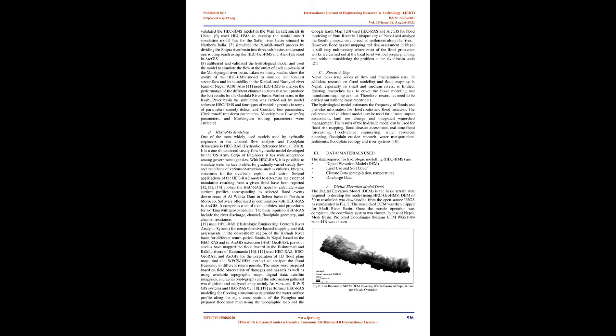The spatial distribution of climate and meteorological data collection stations in the basin is poor. The entire basin is represented by a single set of meteorological component. Therefore, this model used Thiessen polygon method for spatial distribution of rainfall. Snowmelt component was not considered for the runoff contribution in the river basin. The assigned parameters were not necessarily the physical reflection of the basin.